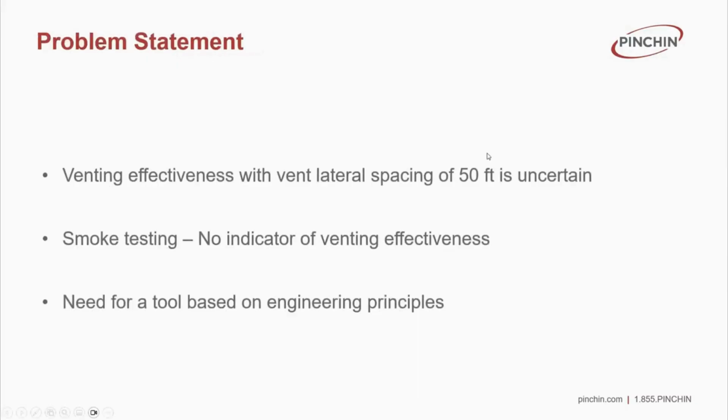So the problem statement is that venting effectiveness with a vent lateral spacing of 50 feet is uncertain, because we do not know, if we space out at 50 feet, whether the entire space between the two vent laterals is actually going to be vented or not. Sometimes we do post-installation smoke testing to see the venting, but it's really no indicator of venting effectiveness.